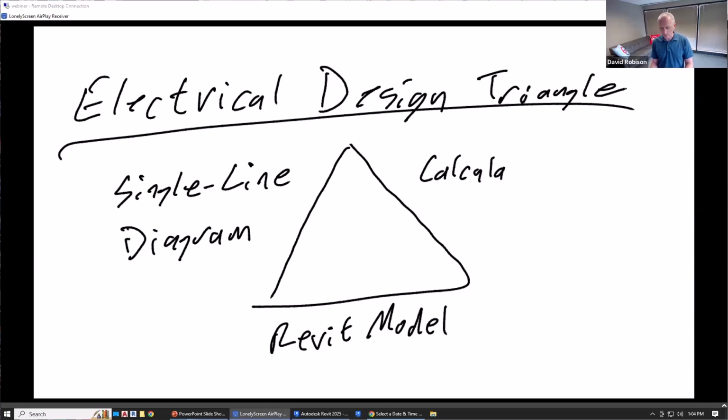And this is where you are sizing your wires, setting the actual wire size, using that wire size to calculate voltage drops, to do short circuit analysis, and things of that nature. So the single line diagram doesn't exist by itself. You actually have these other pieces as well.